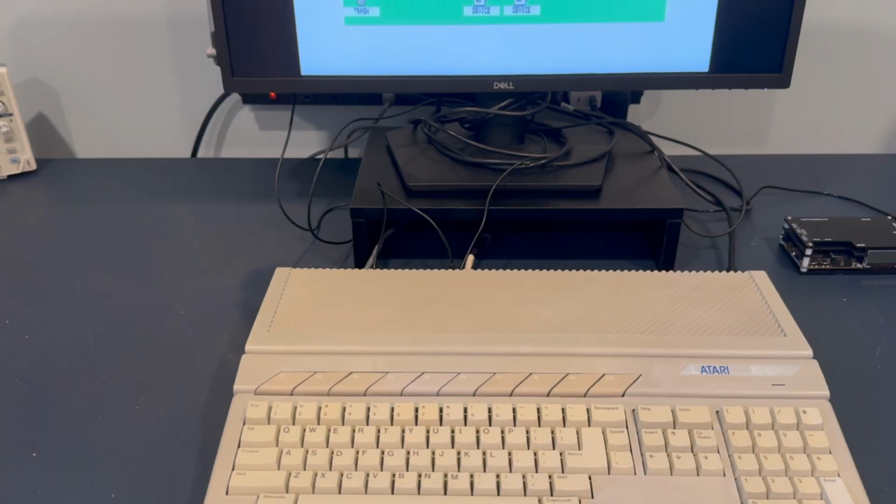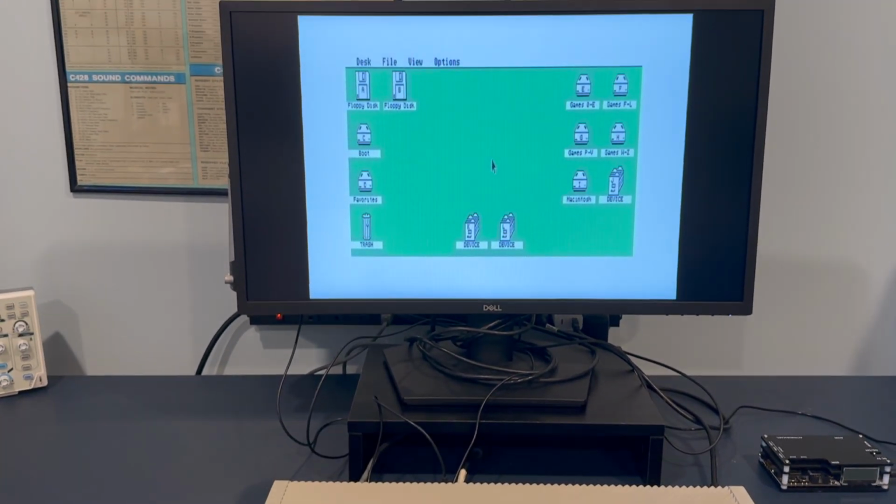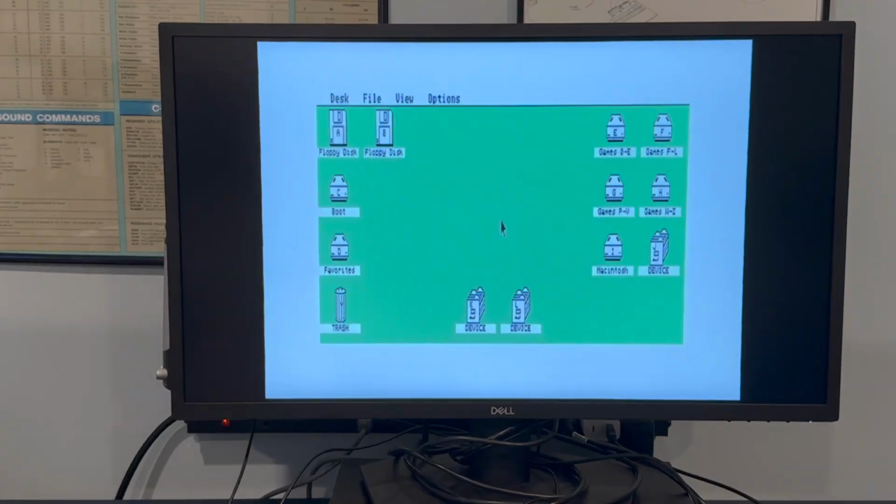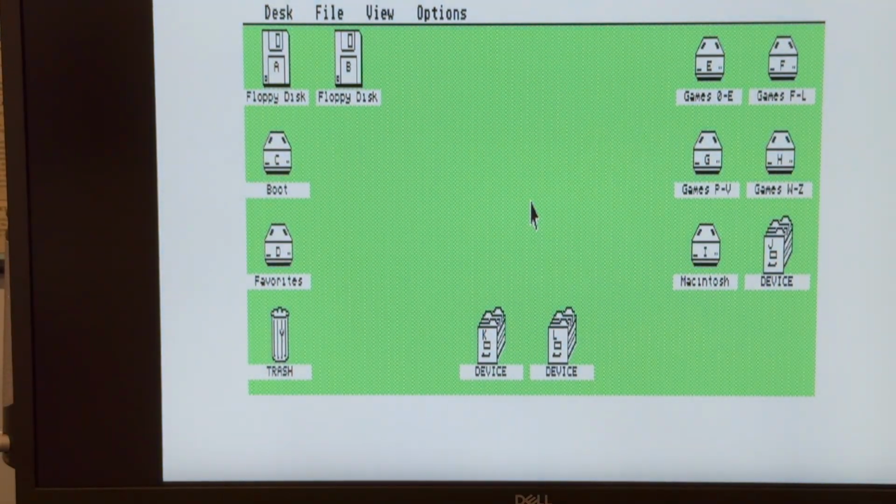You might get that kind of signal, and sometimes you may also get an out of range signal or a message that says out of range, but it's picking something up. It isn't actually displaying, so the color mode only works on monitors that are capable of 15 kilohertz signal. Now, this is an Atari ST hooked up through that same adapter to a 15 kilohertz capable monitor.